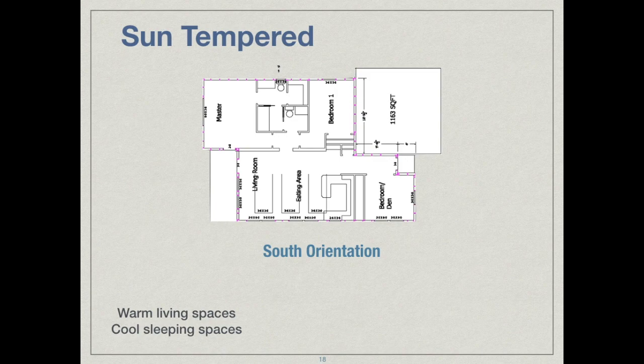Here's some free energy for you, a way to make buildings efficient by spending not a penny more. All you have to do as a designer is think about putting your windows on the south side of the building. Put your living spaces on the south side of the building along with those windows, and therefore those spaces will be more comfortable in the winter, and it will prevent the overheating from having a lot of windows on the east and west.